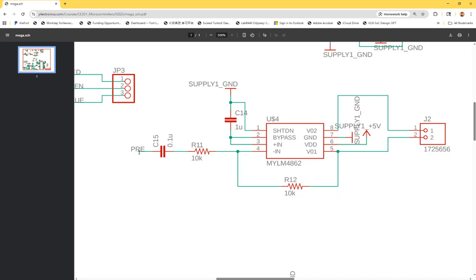The difference is if it's just doing on and off, you see this is a high pass filter, a capacitor. It only detects the rising edge of the on signal. It's giving a pulse. The high pass filter will filter that step function into this, because the rising edge is considered a varying signal, so it will pass the capacitor.